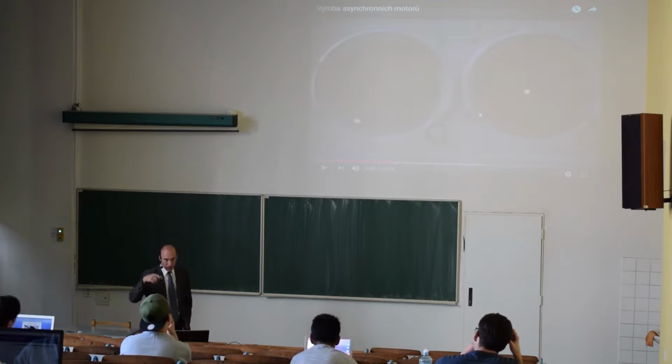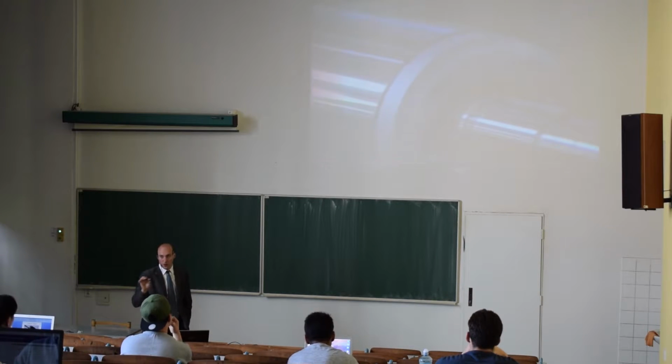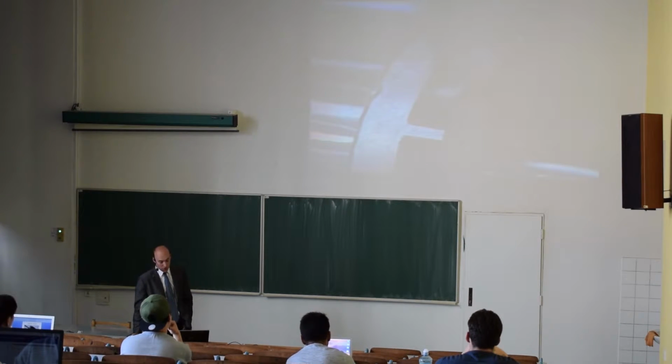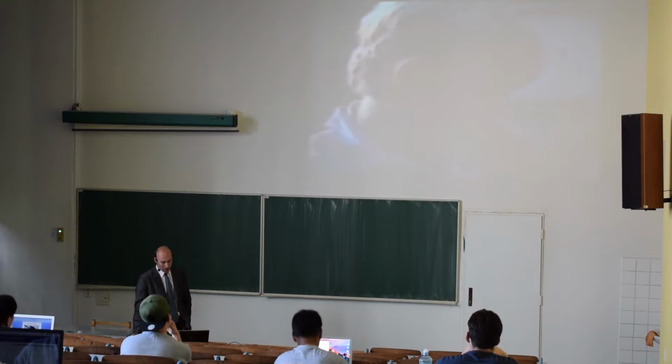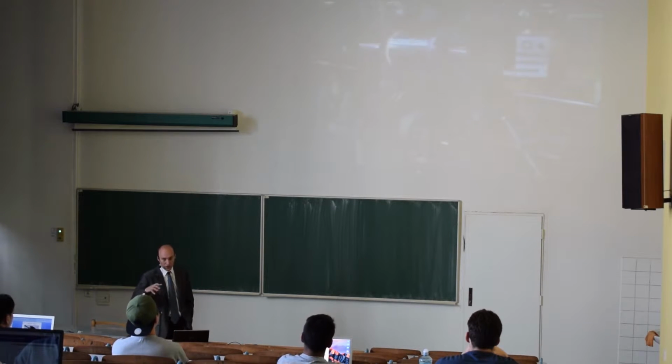So they started, the point should be in the middle when it's balanced, and if it's not, they will be adding or removing weight from correct positions. So now a small weight has been added to the rotor, and it is balanced how it should be. So you see the rotor is done.